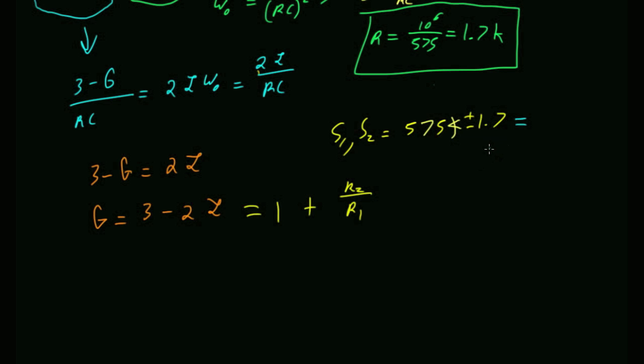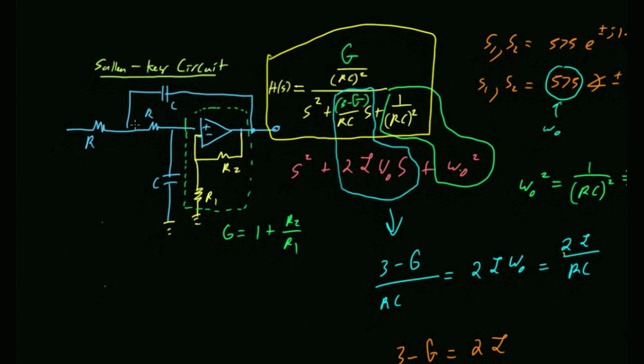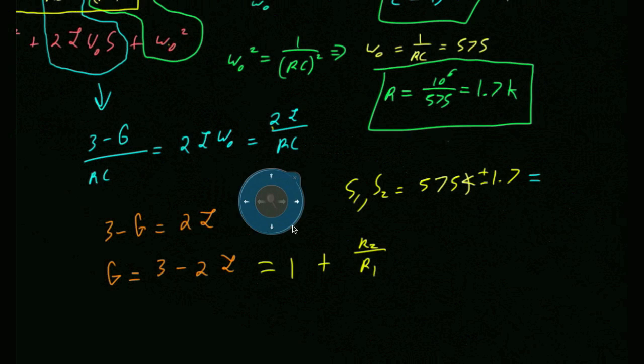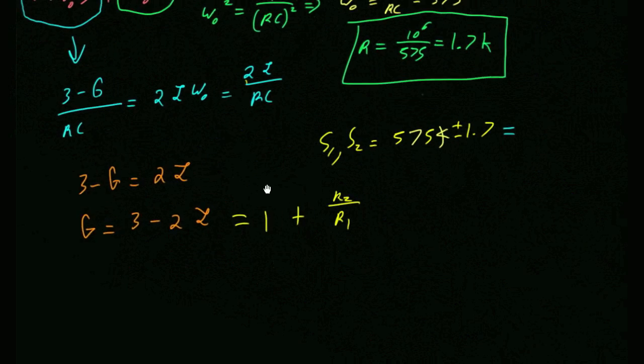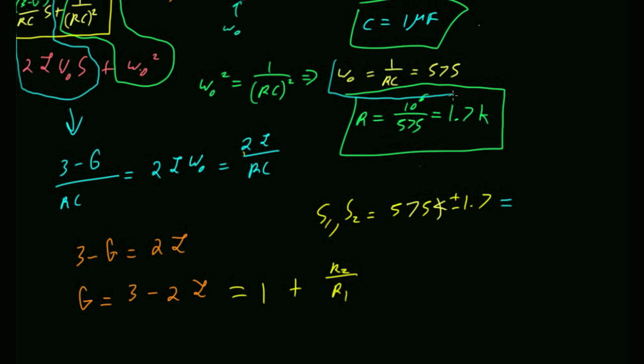No, because there's all this other stuff that happens between voltage in and voltage out. That's voltage in and voltage out of just this little sub-circuit. But now we need to know how to set the gain of this thing in order to get the entire thing to have the value of zeta that we desire. So the problem that we're now having is, we know the value of omega naught, but I need to know what's the value of zeta that's represented by this root. We know for a fact zeta's got to be between 0 and 1 because it's underdamped, because it has complex poles.